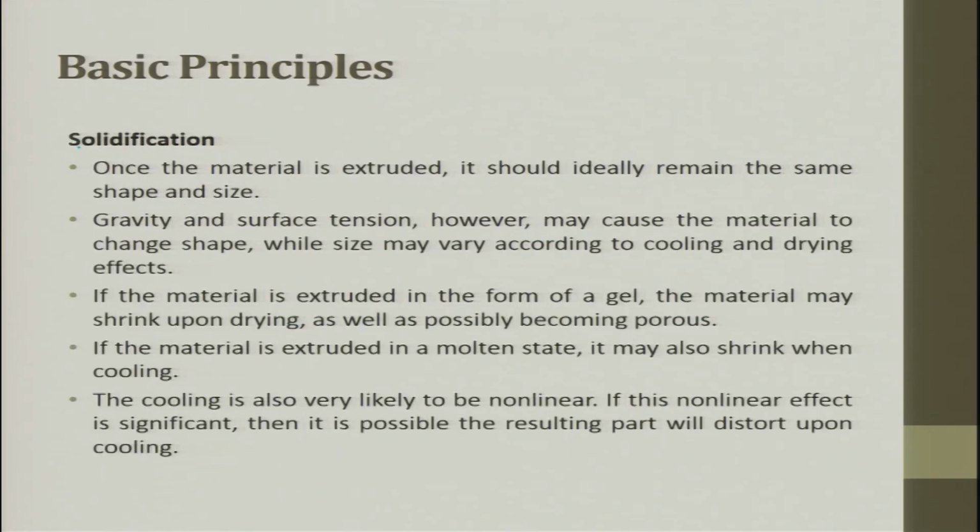The next one is, till now, hopper flowing we saw. Next one is solidification. Why solidification? It will lead to delamination. You want to avoid delamination. So we have to focus on solidification. Once the material is extruded, it should ideally remain the same shape and size.